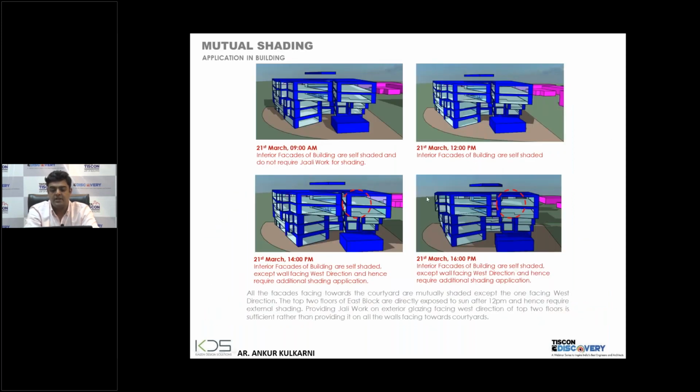If you see these two images, we were very keen to not have any glare coming inside at all. So basically 2 3 different types of glare are there. One is direct radiation, so sun rays falling on your roof are also considered a glare problem. And the second thing is contrast ratio. So say for example in the same room, if one corner is getting a lux level of around 2000 and the other corner is, let's say, 50 or 100, that contrast ratio also causes glare. So here what we try to deal with is, this is a problem. Here the direct sunrays are coming, this is a problem.